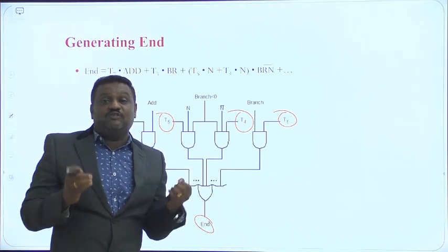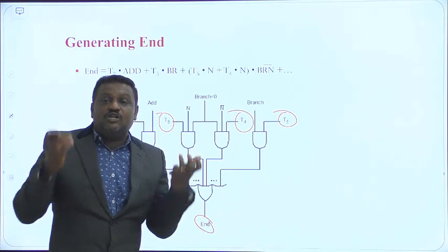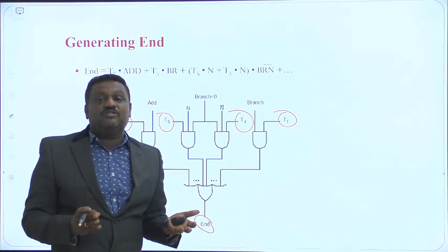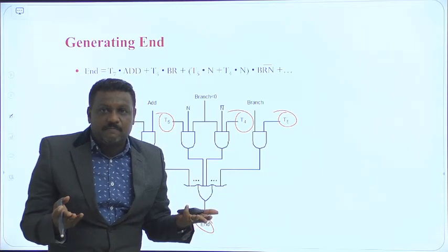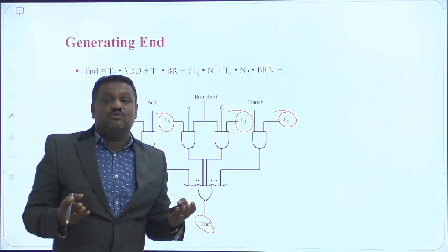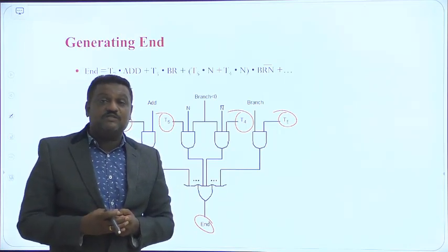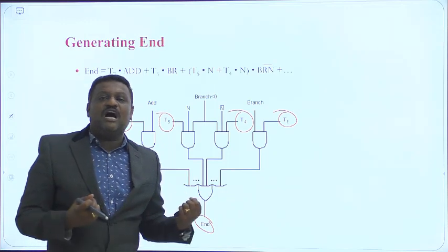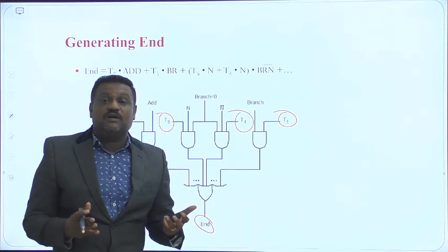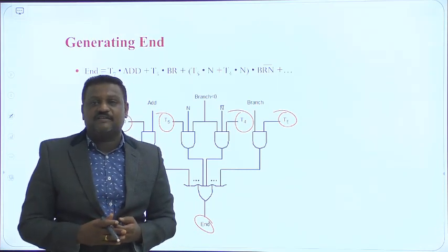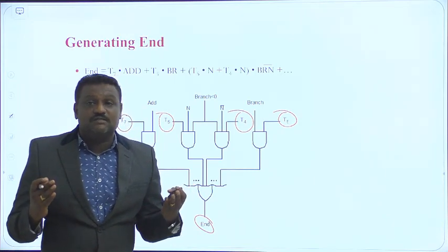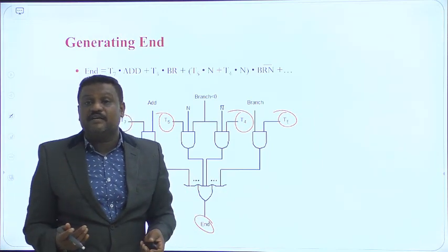Because in every instruction execution, we know that we need different control signals. In order to execute that instruction properly, to do an operation in a proper way, I need different control signals. Those are generated by my control unit. So it is not that easy to add a new instruction to the instruction set. That's why the flexibility is little. But once you are using hardware circuits for generation of control signals, no doubt this hardware control unit generates control signals at a faster rate. I hope you understand the meaning of that: why a hardwired control unit has high speed as well as little flexibility.